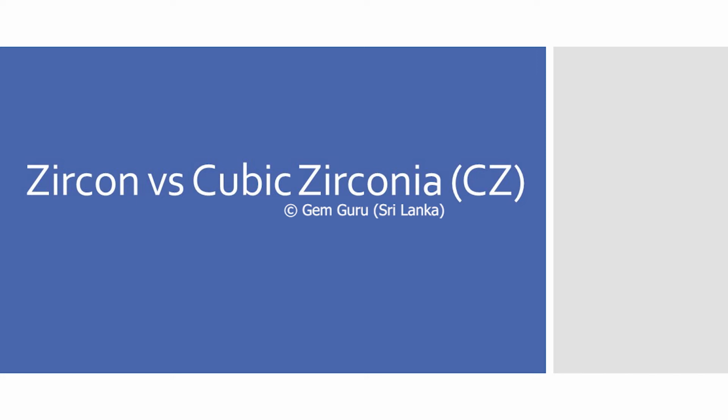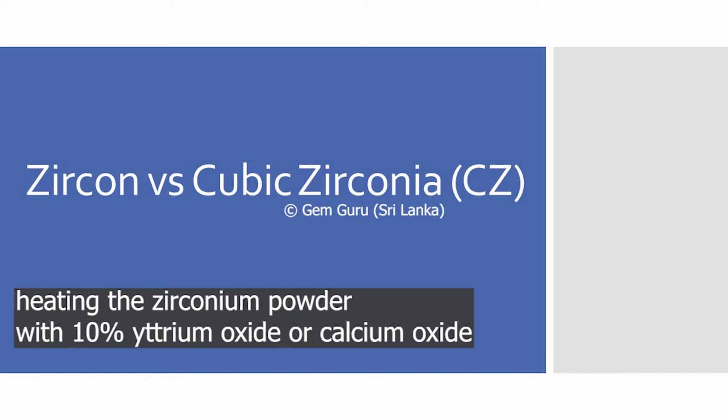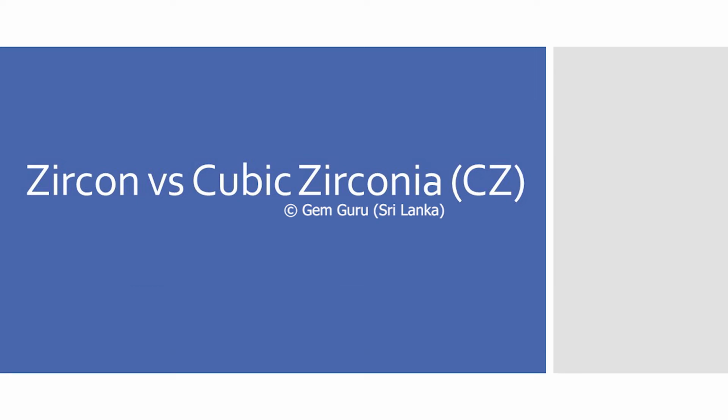The process can be achieved by heating the zirconium powder with 10% of yttrium oxide, Y2O3, or calcium oxide. The yttrium oxide or the calcium oxide acts as a stabilizer to form the cubic crystal inside the crucible. The amount of stabilizer depends on the manufacturer. Therefore, the physical and optical properties of synthesized cubic zirconia may vary.